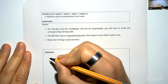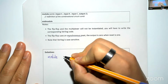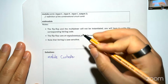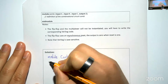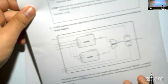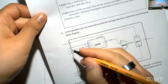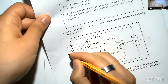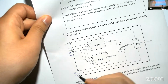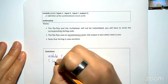Okay, so let's start. This is obviously going to start with a module definition of controller. Now this is going to take some time. Let's start with inputs and outputs. Obviously, you can see from here. We have a reset, 3 input bits named N1, N2, and N3, 1 select signal and a clock signal. So we'll write them, starting with reset.